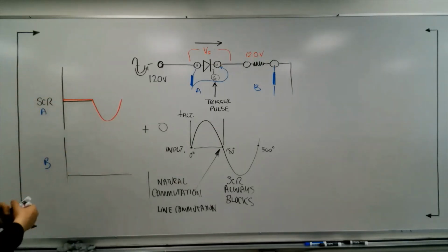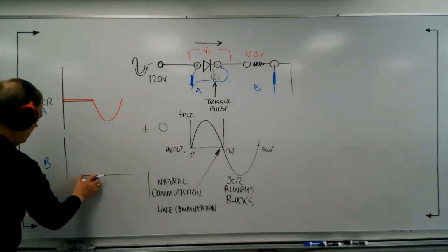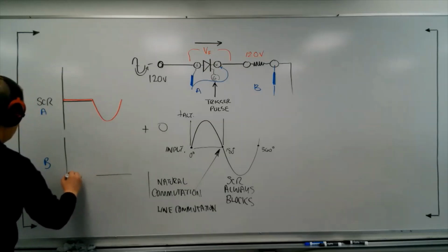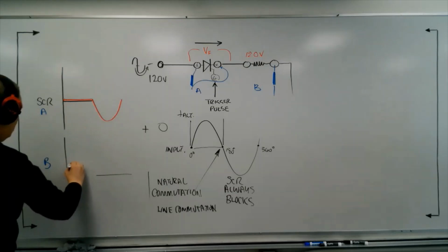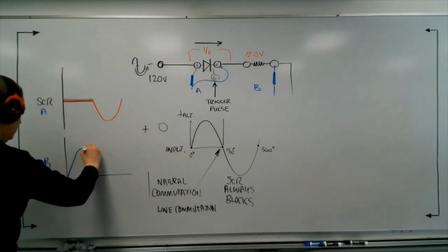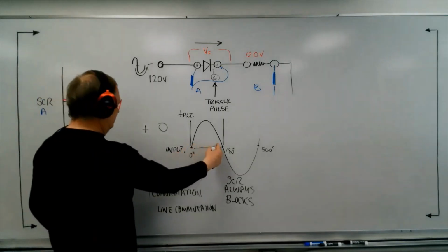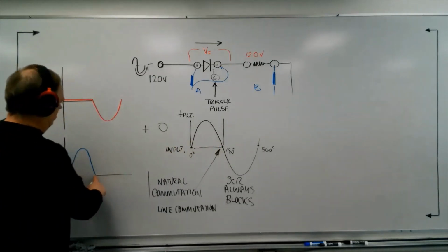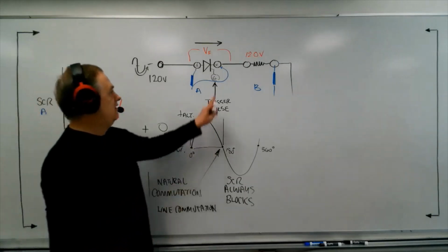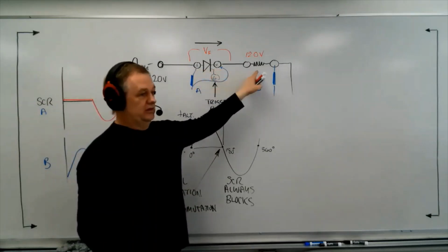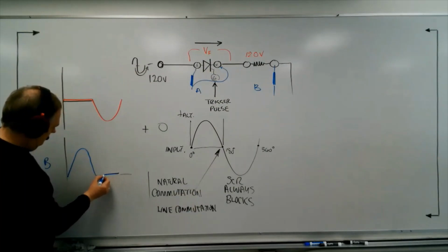Now, what does the load look like during this period of time? Well, it looks like this. We're going to start down here, and we're going to say, if the SCR is closed, the switch is closed, as the AC rises, my load is going to experience voltage like this. And then that voltage is going to fall as we get to the end of the alternation. The load voltage will come to 0. Now, if the SCR is blocking, then there's absolutely no current going through either the SCR or the load. And so that means that my load voltage will look like this during the second alternation.